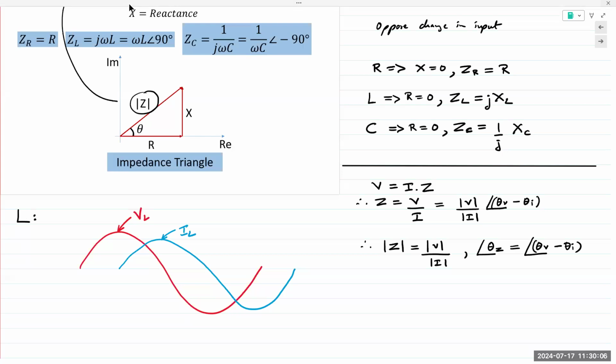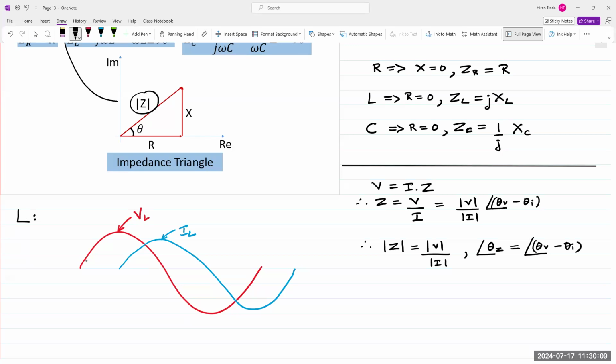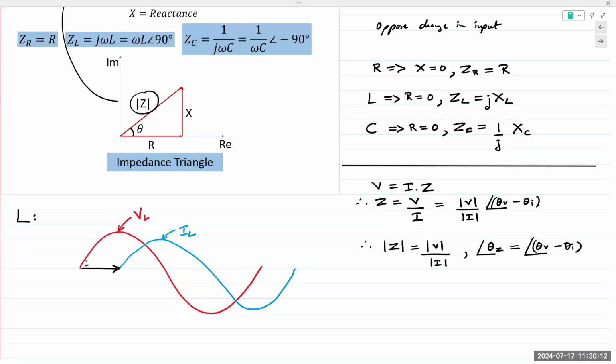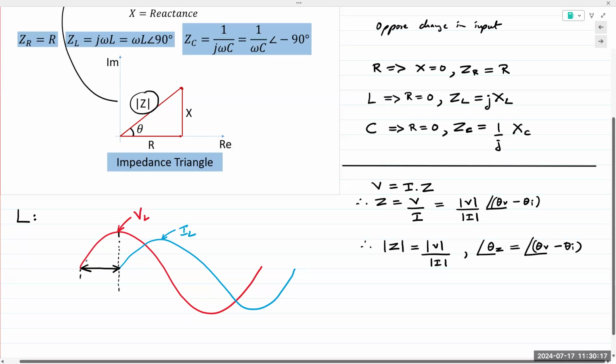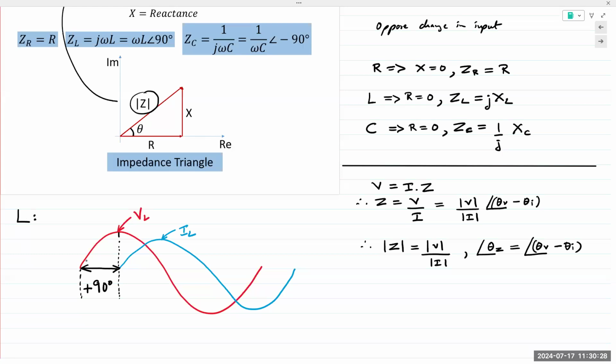And this is indicated right here. If it's ahead, if it's on the left, remember again from earlier in this chapter, all values to the left mean it's in the past, it's already gone by, it's already ahead. So if a waveform is to the left, it means it is ahead, meaning it has a positive phase difference. Okay, so this is ahead.